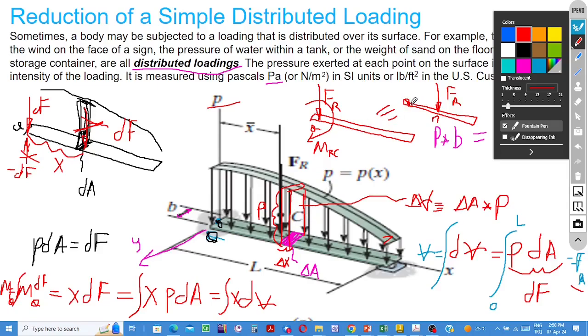Okay, the distance from the reference point to the line of action of this resultant force in this figure has been indicated with this symbol, x bar. x bar is the location dimension relative to the reference point. But at such a distance away, if we apply the resultant force, then its effect is going to be the same as that of the given distributed load.